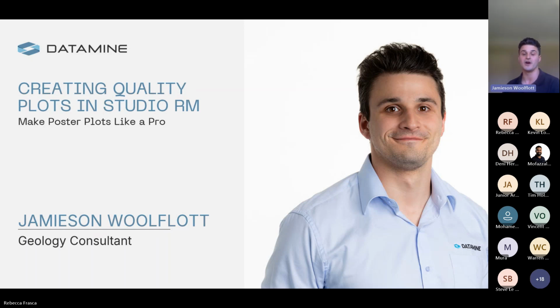So the goals of what I'll be showing you today is to make a nice looking plot, how we can easily print that, batch print it along a series of sections, be they drill sections, pit levels, underground levels, and how we can easily make it reproducible by saving everything we do to a template which can be recalled later. So you only go through the ordeal of configuring everything once, and then it's easy to bring it back.